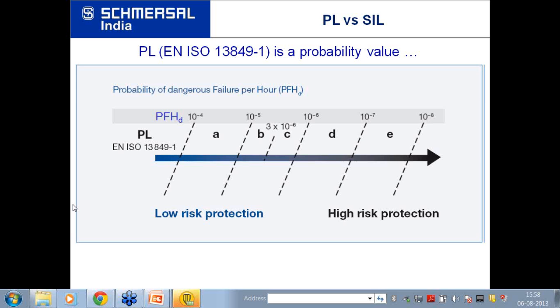It has 2 processors, with 2 softwares from a different batch running on 2 processors. Every input to a safety PLC is actually a dual channel input. You can say there are 2 PLCs which make one safety PLC inside.